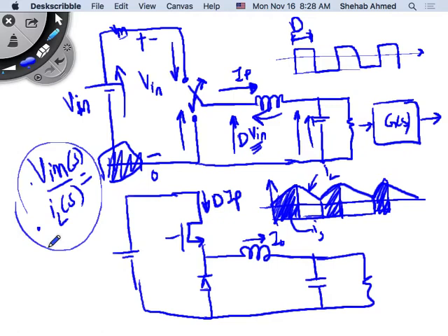But the value is what you see in 420, when you understand how to relate any two variables in a circuit in the frequency domain, you're going to come up with a block diagram or what's called a transfer function. You take that and you stick it in this box. What do you do when you stick it in this box? You know that if you give a certain V input, you will get a certain value for IL. You know that from the relationship from Kirchhoff voltage law, right? But you've added the frequency dependence here.